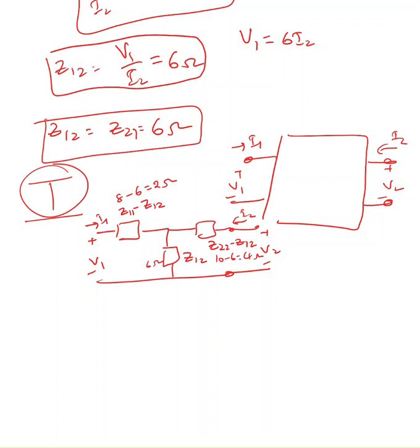So the given circuit, actually I gave you the same circuit, 2 ohm, 6 ohm, 4 ohm. You can clearly see that it looks like a T model, but some examples might have more than 3 elements and they might be connected in series, parallel, or star, delta. We don't know which connection it is. Still we can represent them in this T model as long as z12 equals z21. So as long as that's a reciprocal network.